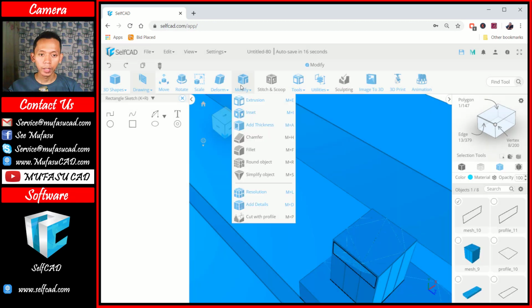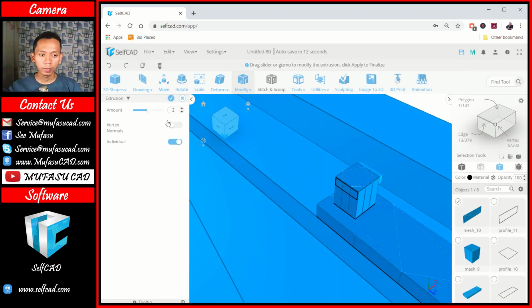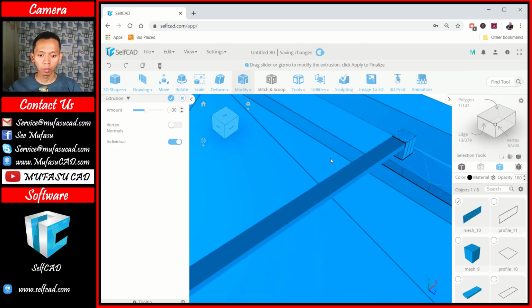We can use the extrusion command. The next I will extrude with minus in here. You can move to this point. Okay, I will set into minus 10. This is for minus 10. We set again about minus 30. Okay, this minus 30 is too long.